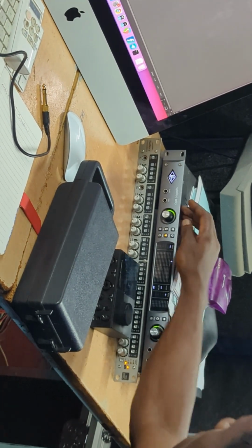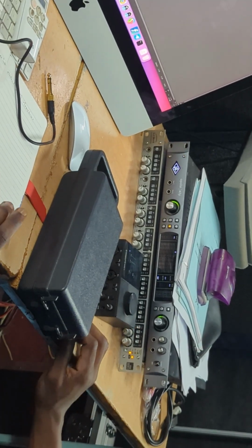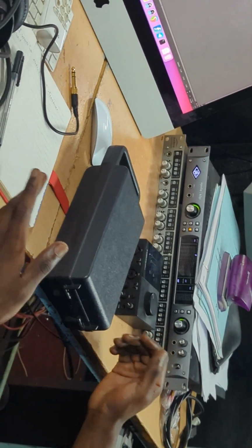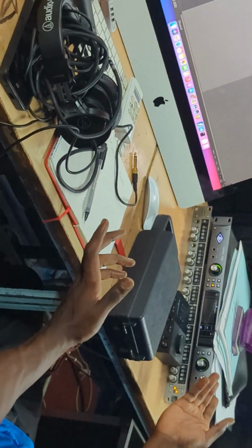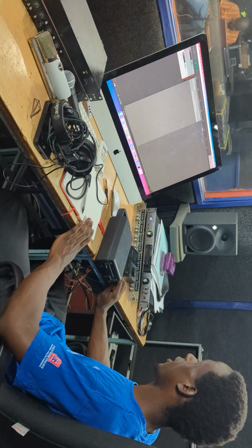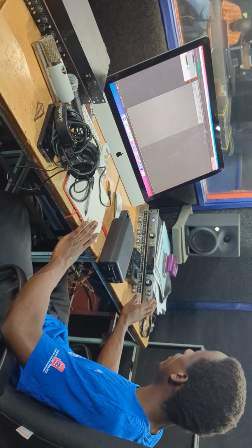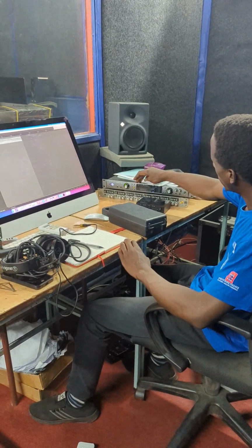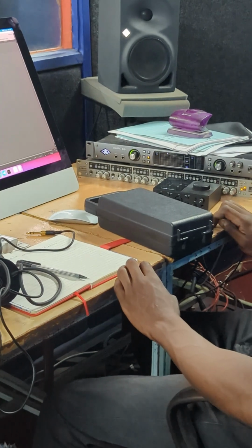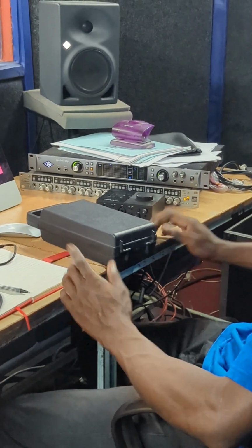The analog to digital audio converter converts the analog signal into a digital signal through a process called sampling. As I mentioned earlier, I talked of the sample rate, which is the rate at which a number of samples are taken, and sound is supposed to be sampled at twice its highest frequency. And the digital to analog converter converts the digital signal into an analog signal, which can be converted by the speakers into sound.